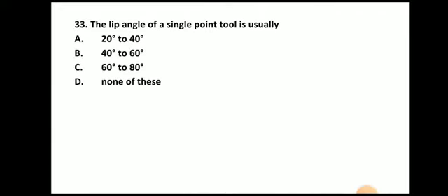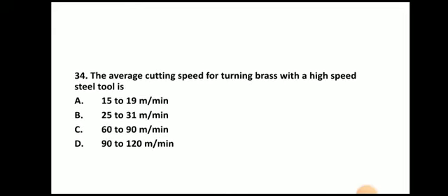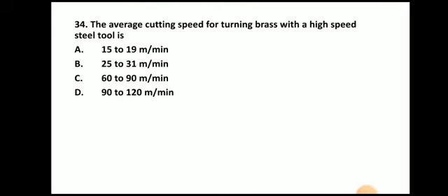Next question. The lip angle of a single point tool is usually. The answer is 60 to 80 degree. Next question. The average cutting speed for turning brass with high speed steel tool is. The answer is 60 to 90 meter per minute.